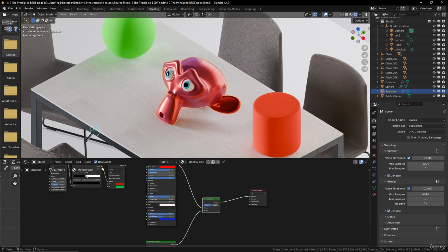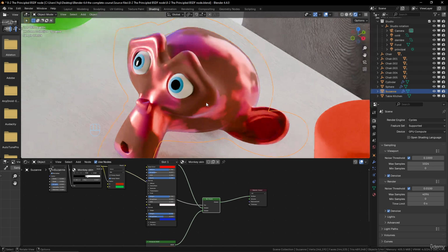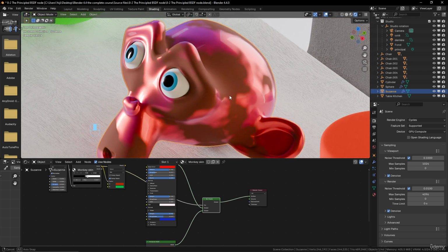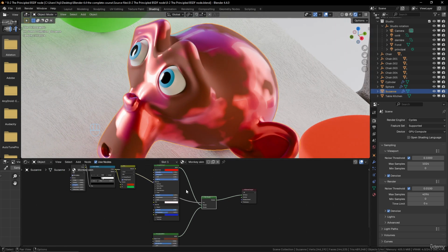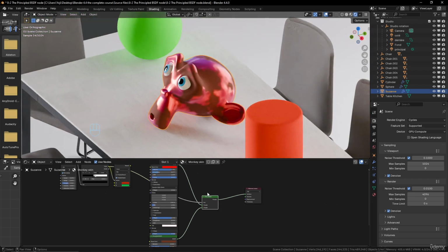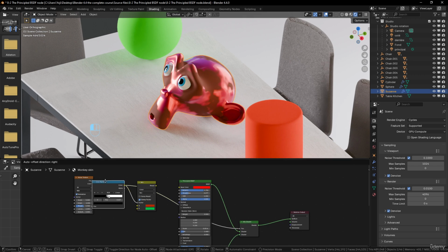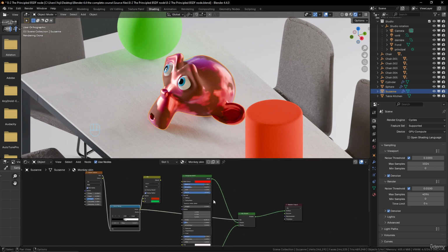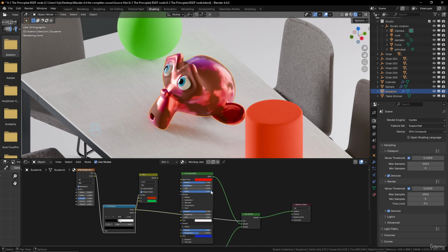And let's say we take this information here and put it there. So now you have the shader that will be two shaders basically. We have the paint shader and the rust shader, and it's mixed by this color ramp. So it's another way of mixing shaders here, as you can see.